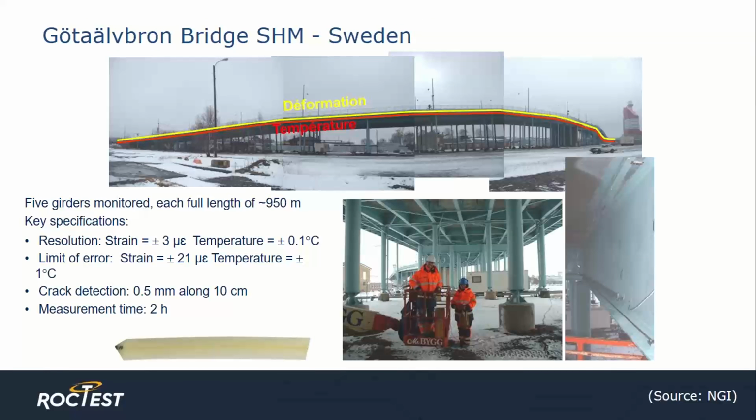The recommended solution was to use 5 runs of SMARTape along the entire span of the bridge, as seen in the upper photo. The support beams to which the SMARTape is affixed are shown in the bottom 2 photos, with the rightmost photo showing the tape. It's glued along the bottom edge of the steel beam.